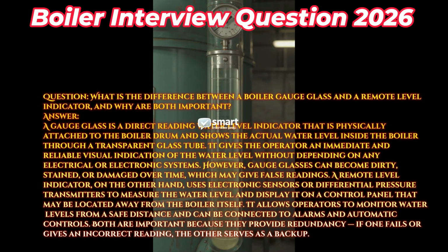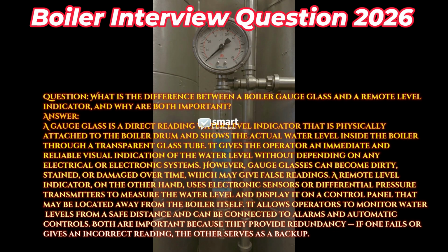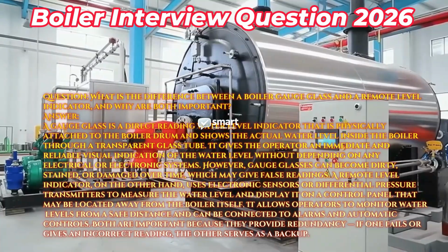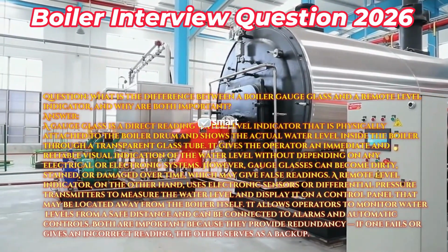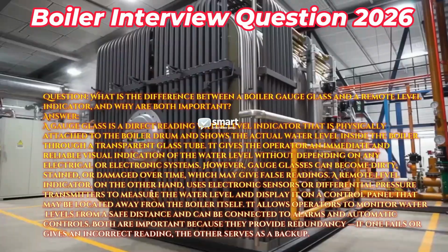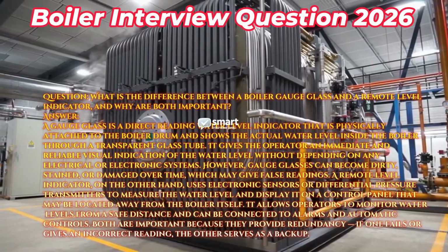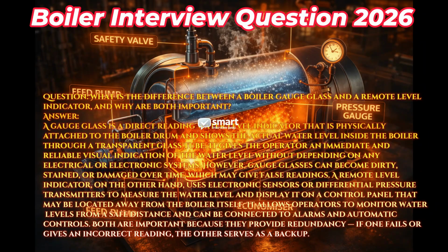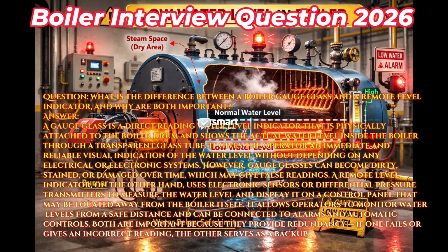Question: what is the difference between a boiler gauge glass and a remote level indicator, and why are both important? Answer: a gauge glass is a direct reading water level indicator that is physically attached to the boiler drum and shows the actual water level inside the boiler through a transparent glass tube. It gives the operator an immediate and reliable visual indication of the water level without depending on any electrical or electronic systems. However, gauge glasses can become dirty, stained, or damaged over time, which may give false readings.